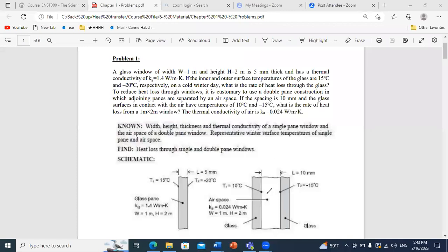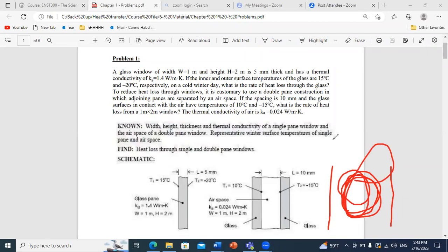From one side, it's true that we are increasing the thickness of the air layer, so we are reducing the conduction flux, but at the same time we know air is a fluid, and if you give it enough space, this will increase the freedom of particles to move, and then you can have currents of air which will lead to convective heat transfer, because whenever we have a fluid moving over a surface, we can have heat transfer by convection.